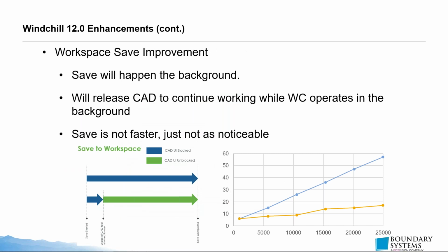All right. One of the things you will see as you start to work, especially when you have large workspaces, is that the workspace save has improved. The improvement is that a lot of the save work is done in the background. So what you're going to see when you're now saving is that your Creo session is going to pause while it saves from your Creo session to your workspace.